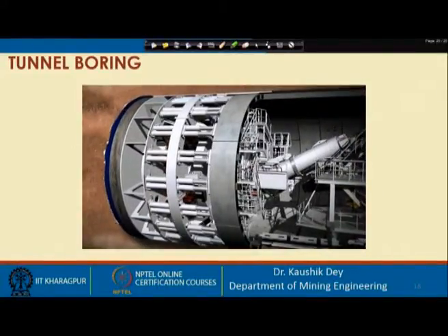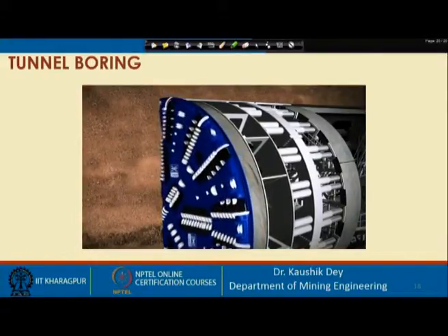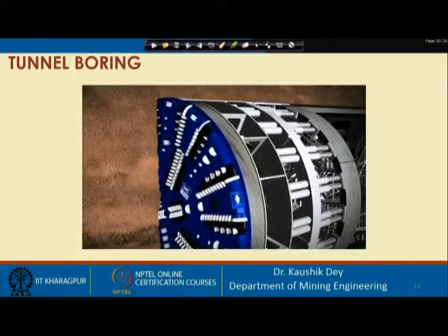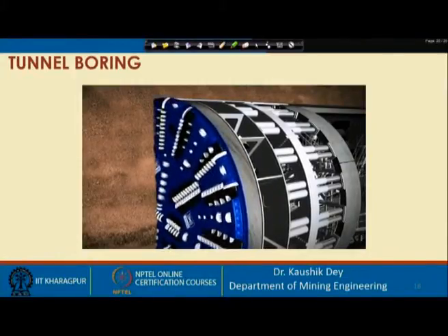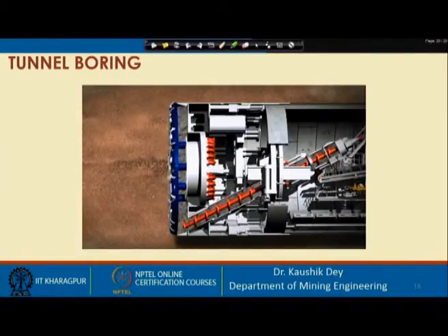The first part of the TBM's work is the tunneling phase. So, you can see the earth pressure balanced TBM has a rotating cutting wheel, which is pressed against the tunnel face by hydraulic cylinders. The material is being cut and crushed in the chamber. Inside the cutting wheel, you can see the disc cutters and scraping tool loosen the material, and finally the material is coming into a screw conveyor.